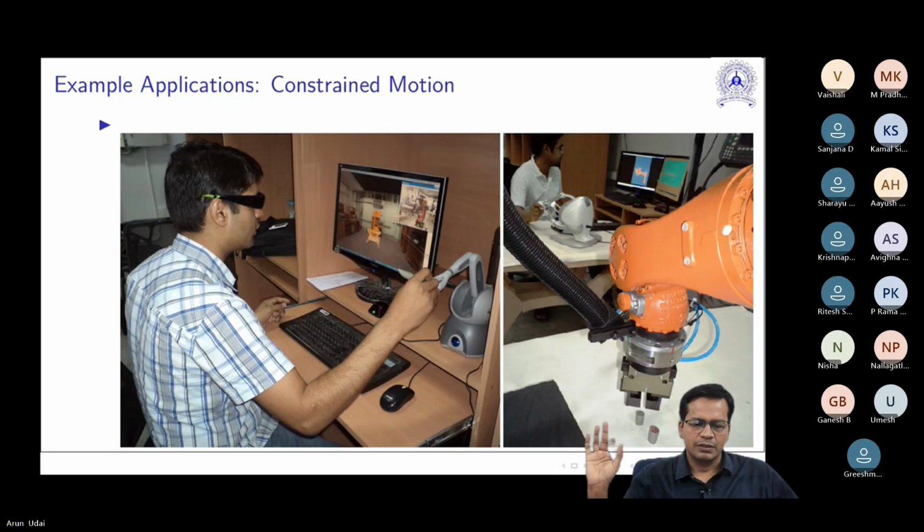but it can also feel the forces which are felt by the robot. So essentially, it has a force torque sensor which is sitting here. So whatever forces are seen by this while picking up these pellets on the table, those forces are reproduced here in this haptic device. So it is a joystick and it can make you feel the forces.